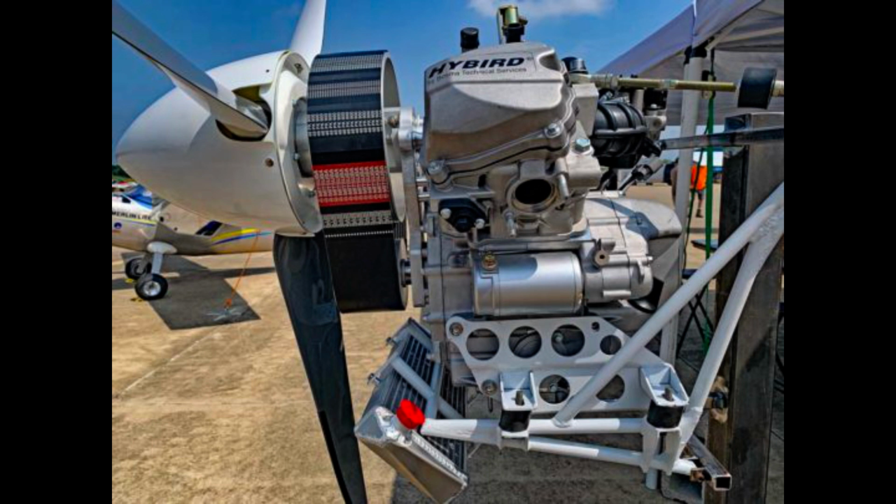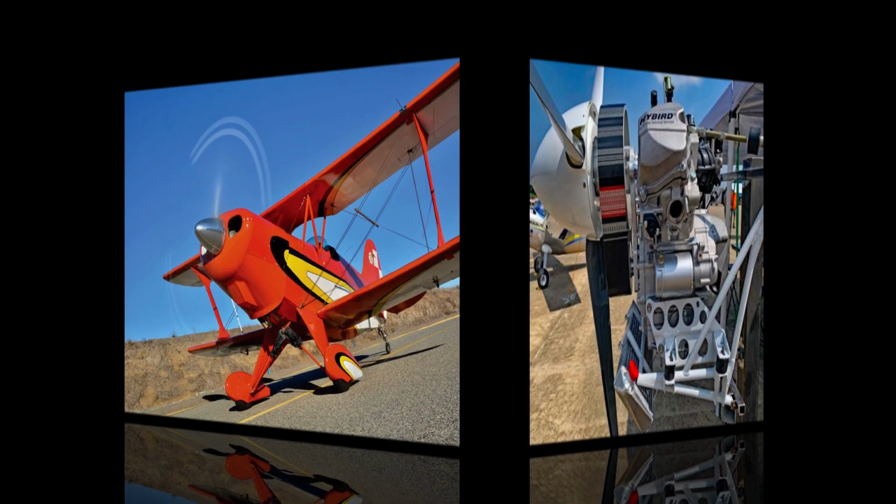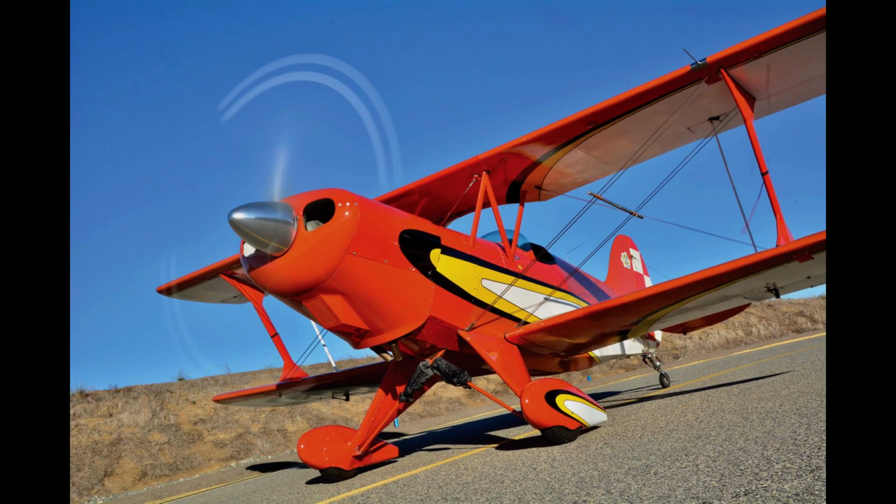Additionally, the crankcase has steel bearings set into the aluminum which need to expand together or the bearings could slip. Many two-stroke engines have steel bearings that normally hug the walls of the aluminum engine case. The crank spins within the donuts of those steel bearings. If the engine heats too quickly, the aluminum case out expands those steel bearings and the crank causes the bearings to start spinning along with it. If those steel bearings start spinning, it can ruin the soft aluminum walls of the case, which is very expensive.